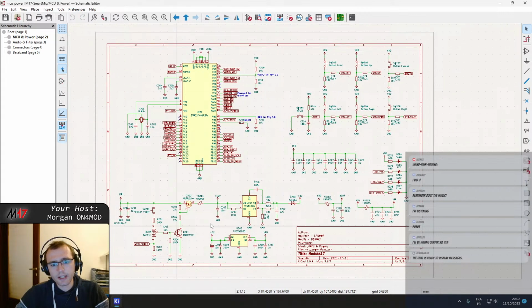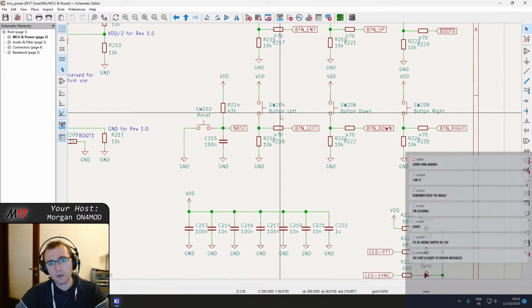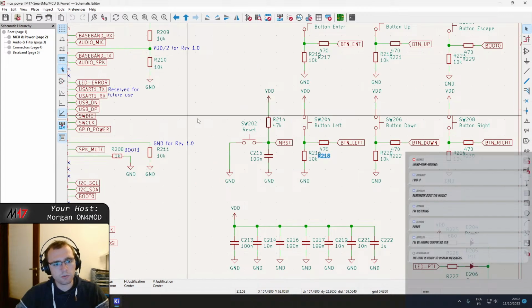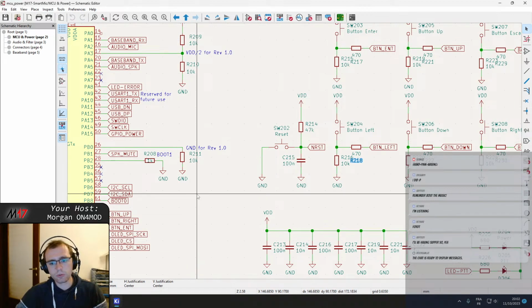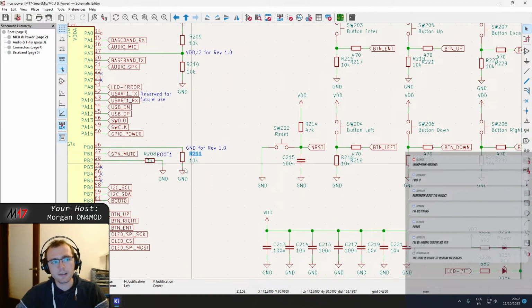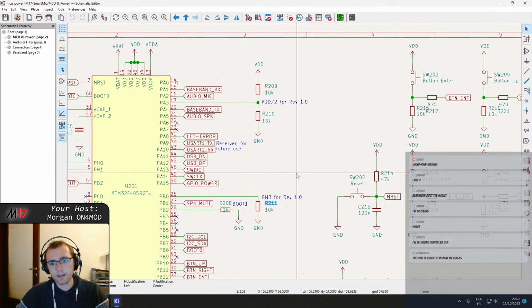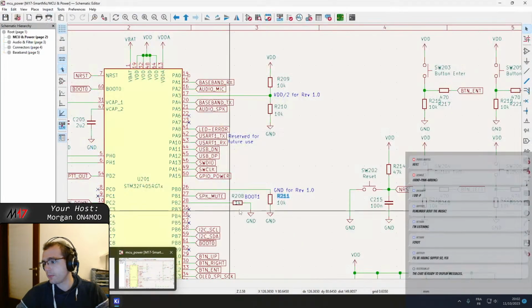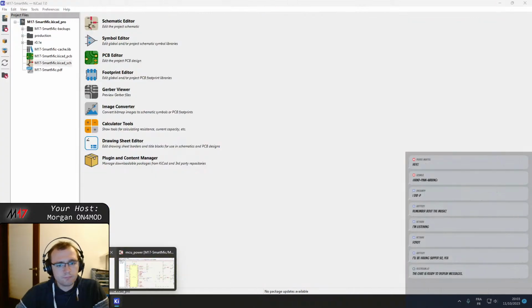So yeah, renamed all the components so now it's the style I prefer. All the components start with a multiple of 100 depending on the page on which they are. Which means that if you see a component on the board, R211 for example, you know that you will find it on the second page of the schematic. I prefer to do it this way, and on Module 17 the component numbers aren't printed on the board anyway, so the number definitely doesn't change anything to what we do.